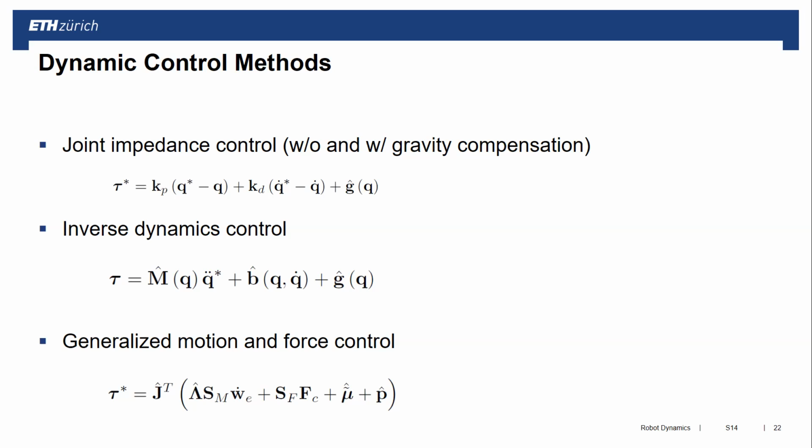a PD controller for every joint, which means in a physical implementation, it's a spring damper element. So I have my arm here, and I apply a spring damper element to every joint. What it does is this: it oscillates a little bit and comes to a configuration which is not the nominal configuration. Every joint has a little bit of an offset. We said we want to compensate for this in the quasi-static setup.